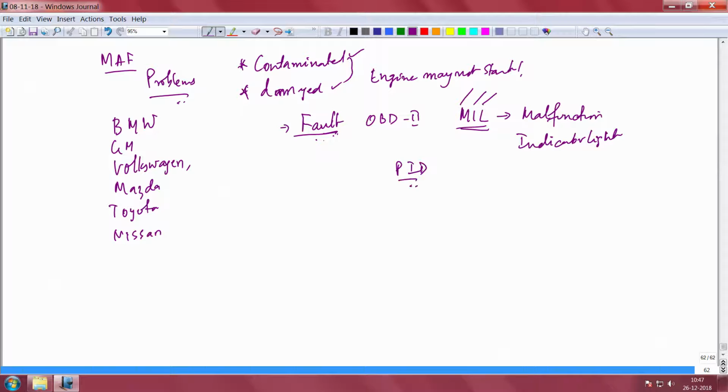Then you know your panel is clear and it is good to start and good to go. All that means that it is doing some self tests, some self diagnostics, and if that light does not go, the MIL light does not go, clearly it will record it in the ECU and you can retrieve it. It will record it in terms of some OBD2 data. It will indicate a PID, the parameter ID, and the moment you connect a scan device to it, you should be able to read the parameter ID and find out what that fault was.